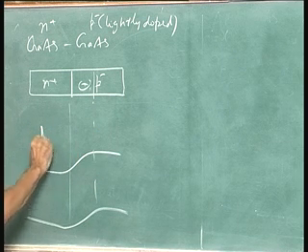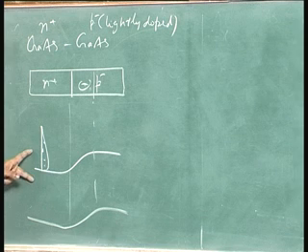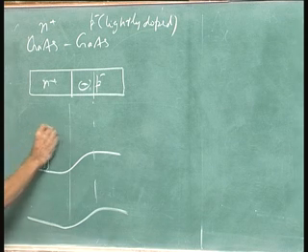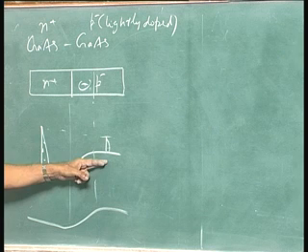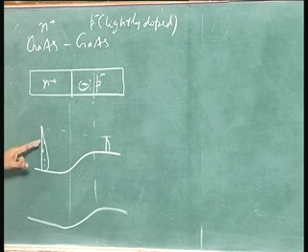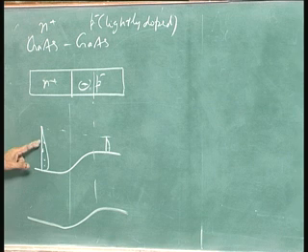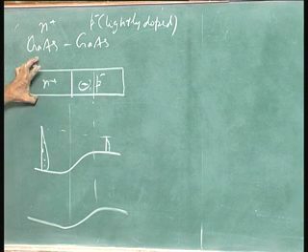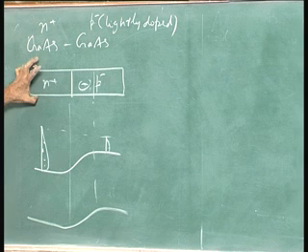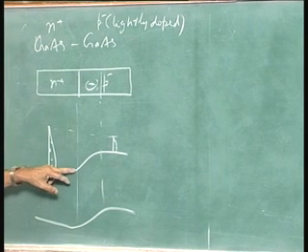So, in the case of single crystal, you get homojunction. If you get that potential barrier, you get more potential barrier. I will discuss again some details about this in the next lecture, because I do not want to hurry it up. So, what I am telling is there is additional potential drop here corresponding to delta E_c. That means there are additional electrons compared to the homojunction here. How many electrons are there depends upon how much delta E_c is.